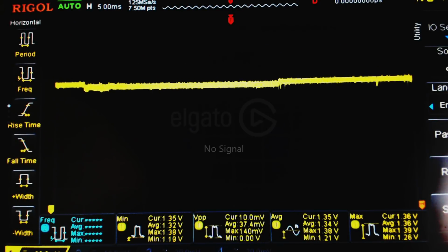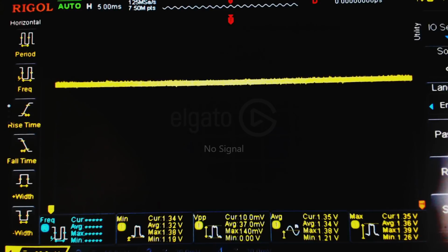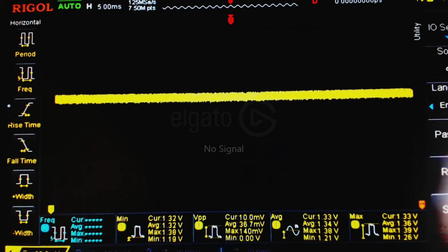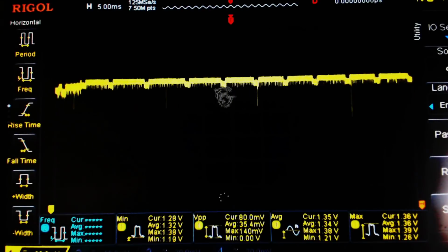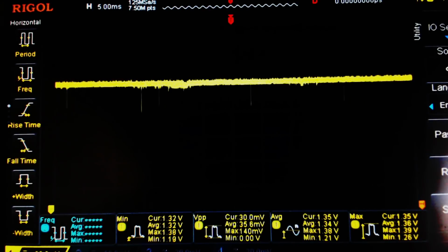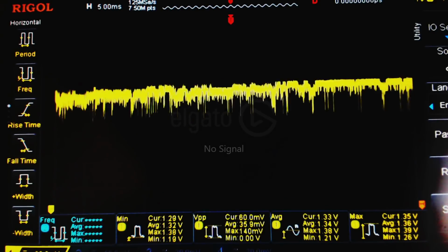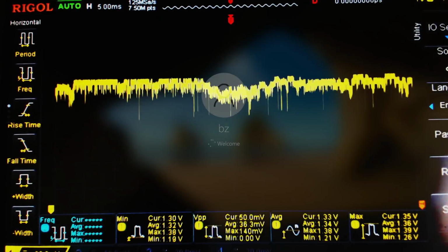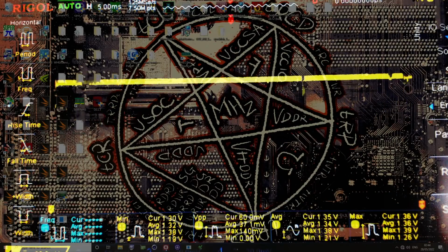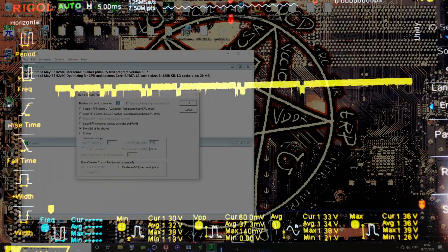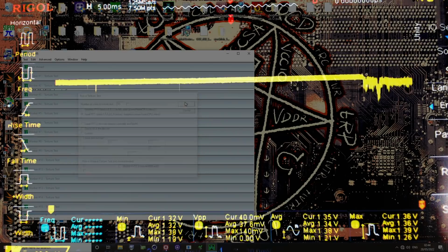Yeah, but I like... I'm guessing Gigabyte basically tested this, and they realized that, wait a minute, we'd have to write custom control loops for every single switching frequency setting, and so they just didn't give you switching frequency options. Whereas MSI just kind of left the switching frequency setting in the BIOS for reasons I don't understand at this point, because it's just worse as far as I can tell.